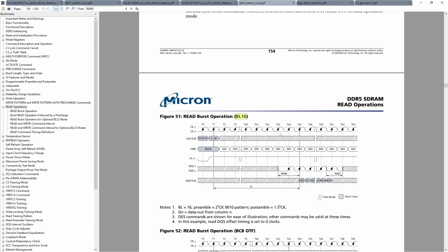And so with DDR5, with the longer burst length, in order to maintain that 512 bits of data per read, we now have the 32-bit memory subchannels. So now, if you want to read just a single byte of data, you still get 512 bits of data, but that's more efficient than reading 1,024 bits of data every time you want a single byte of data, right? A byte being 8 bits. So evidently, 512 bits per read seems to be some kind of happy sweet spot that the CPU and DRAM manufacturers agree on.